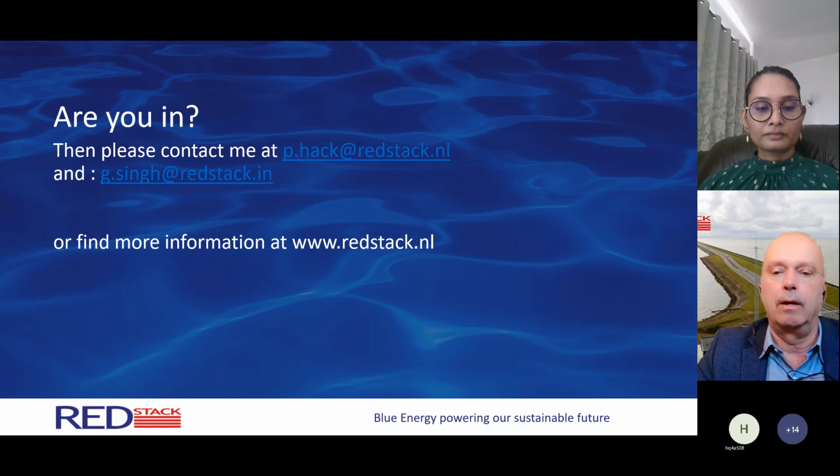Second is, we will be pre-treating the river water and also the seawater before it flows into our equipment in our plant. And I think we can use, let's call it a two-step pre-treatment system. First, a pre-treatment system to take all the garbage, the rubbish, the plastics, the plastic bags, whatever is floating around, the coarse stuff.